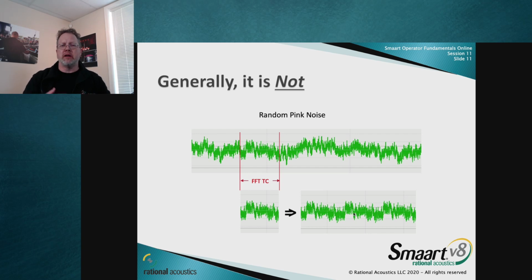Even worse, any of you that have ever done wave editing, if you just take two random wave files and splice them together without dealing with that transition, you're going to get a pop and noise, and that's exactly what you get mathematically, is just crap. So the data window functions are there to push the beginning and end of that wave down to zero so that you have a smooth transition. The trade-off is you get a raised noise floor, but you get much better data and a much more accurate measurement.